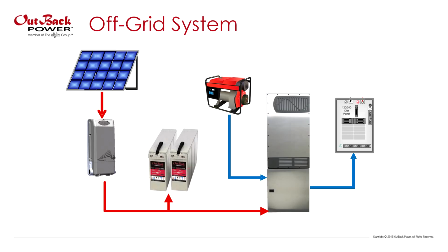So this is what a basic off-grid system would look like. The top left, we have our PV. So this could be somewhere between 130 volts to 600 volts DC. It could even be beyond that as well, but generally we'll just say that. Next is the charge controller. So this is a DC to DC converter. Our PV will very likely be at a significantly higher voltage than our batteries, which would normally be somewhere between 12 volts to 60 volts DC typically.